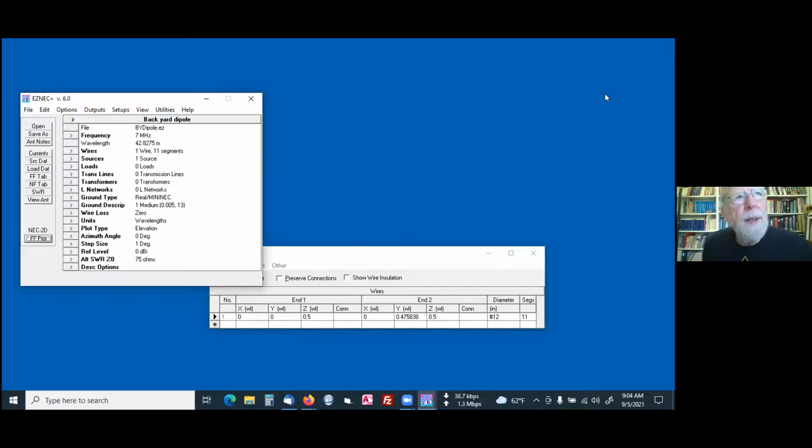So that means if you put 100 watts into an antenna the size of a toothpick or a 30-element beam up 500 feet, 100 watts comes out of each one. Now, in the case of the short antenna, almost all of that power coming out of that is in the form of heat. In the case of the big beam, hopefully it's very little heat and it's almost all radiated. But the 100 watts does come out.